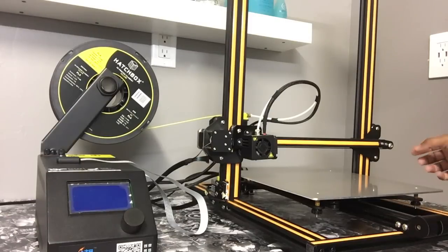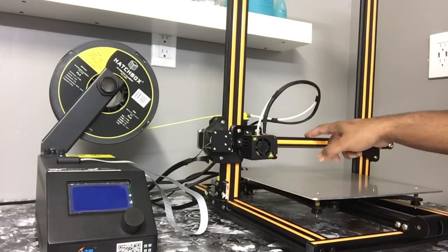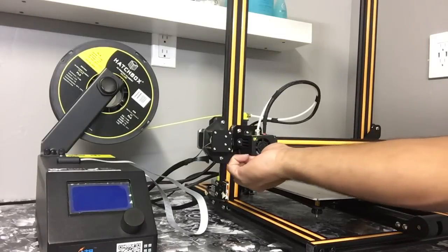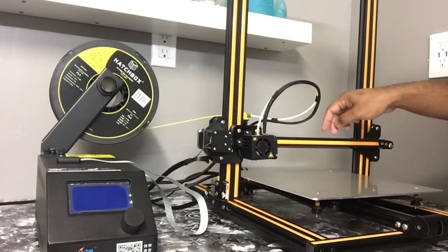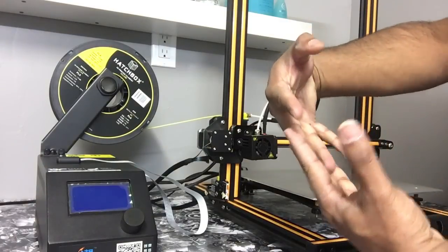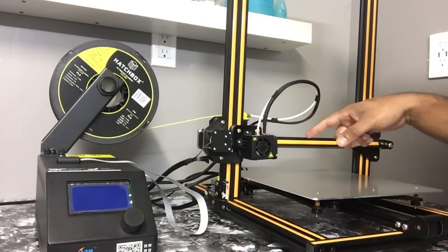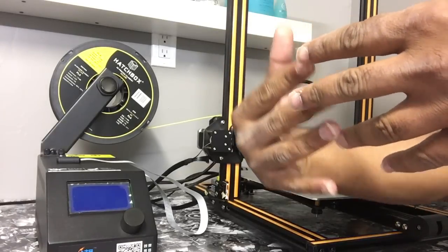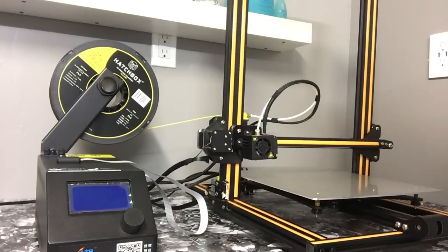and this way there'll be no issues with the print, because when you're printing, let's say for example your belt is loose, there's gears here like little teeth, and then the actual belt has teeth, so it connects as it moves around. So for example, if your belt is loose, you might skip a connection like that, and that's going to show up in your print as imperfections, which you don't want.